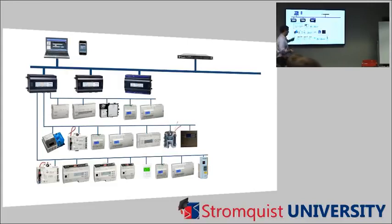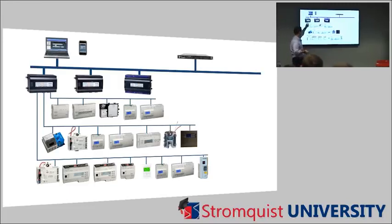All the same. Also remember that the Jace can accept all of these. In this scenario, I should probably take those off. They're just up there, not connected to anything, just there for looks. You'll notice that all this is wired back into this one Jace, and it's all different. So the whole point is that all these different languages, communication protocols, all go back into that one Jace, and the Jace does the translation for them and spits it out.